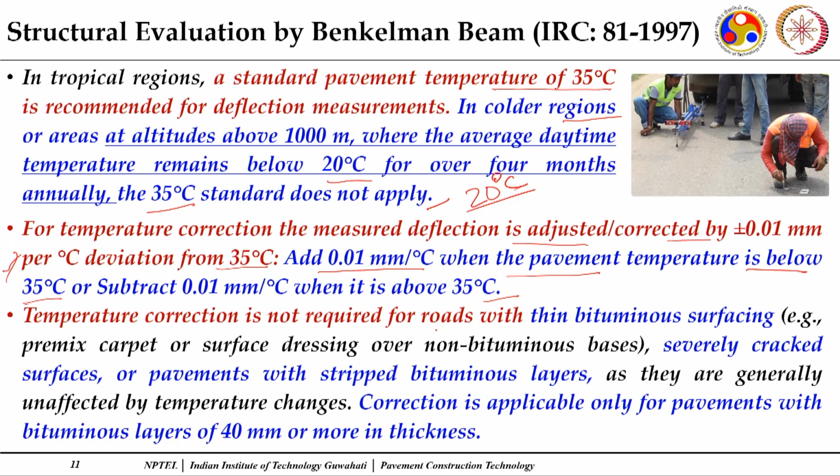So, temperature correction is, as mentioned, specifically because of the change in the binder stiffness. Now, there may be certain pavements which are very thin, where you do not have a good amount of bituminous layer, thin surfacings. Then you do not need to apply these corrections, specifically for premix carpet or surface dressing.